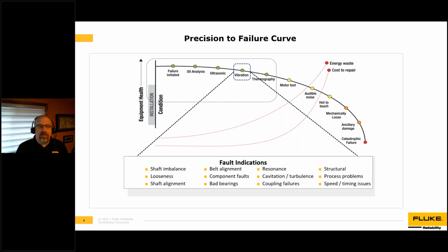Early stage indicators include things like oil analysis and ultrasound. Oil analysis tracks wear particles and additive depletion. It's an excellent maintenance practice where degrading results are an early indicator of problems. Ultrasound can detect lubrication issues and metal on metal contact, providing insight as to early evidence of bearing faults, but it can result in premature repairs, and that shortens the lifespan of the equipment.